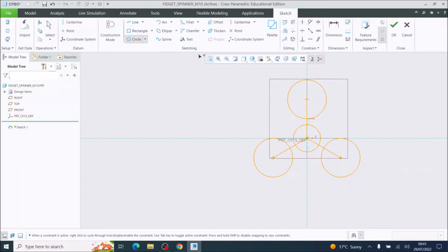Okay, now I'm going to choose the circle tool again, and this time I'm going to draw in a smaller circle on the top. Be careful that it doesn't go green. I don't want a green highlight to come up because I want to set this at a different dimension.